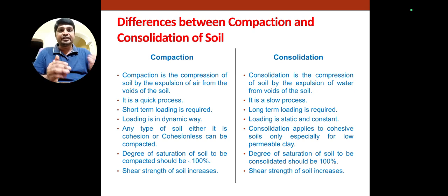happens in fine-grained soils such as clay and silt particles, which have a very small void ratio and less permeability. That is why the expulsion of the water takes place over a very long period of time. That is the consolidation process.